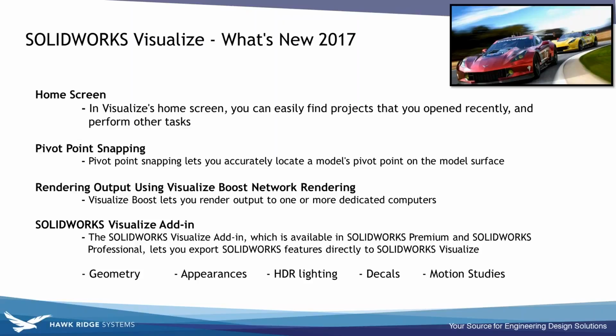But that also exports your geometry from SolidWorks, the appearances, any HDR lighting from your scenes, decals, which is great, right? Because you don't have to re-put those decals on in Visualize, and then also your animations, your motion studies. So if you have gears and motors and mates and everything that are running this animation, you can push that out, bring it to Visualize, and render it in photo quality animation.